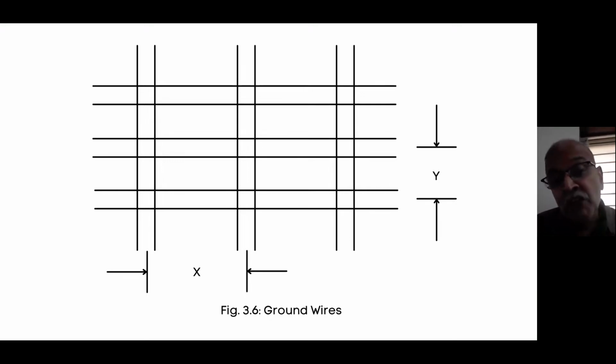These ground rods have to be laid at the mirror reflection of the top ground wire. That means you have to dig a pit as deep as the height of the tower. So digging is costly, obviously. But only one such ground wire is enough. But people prefer counterpoise wires because the system is cheaper.